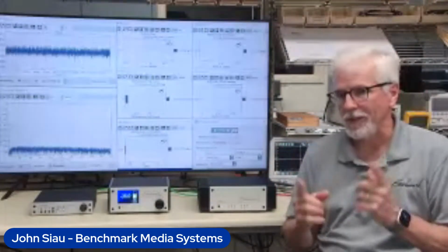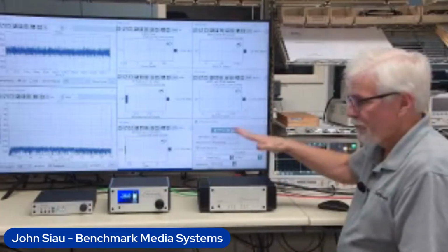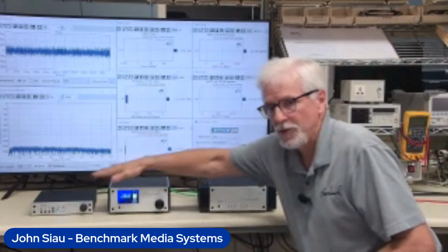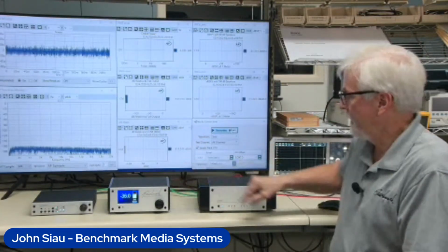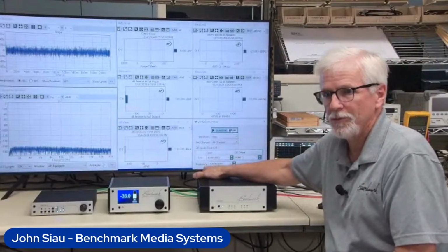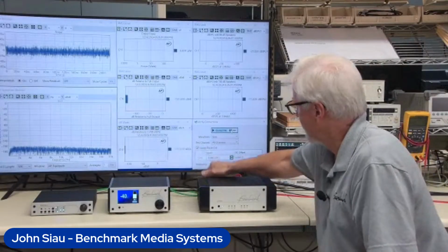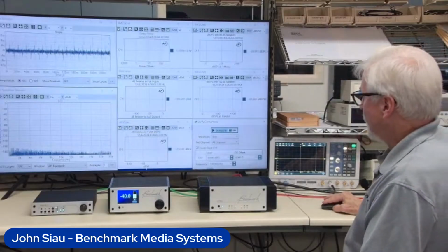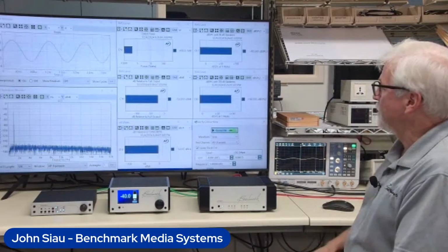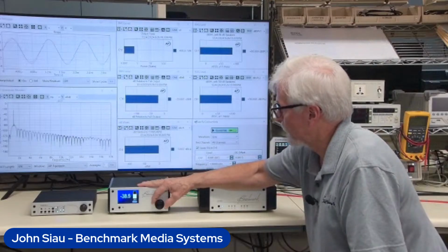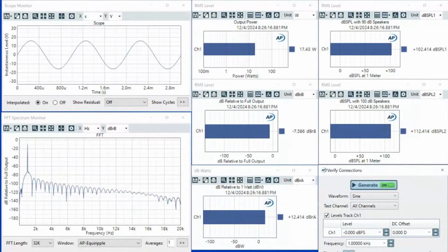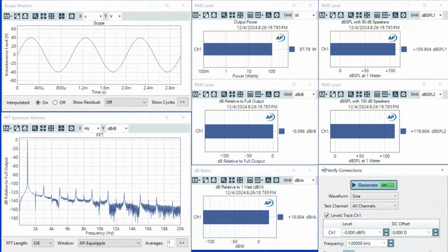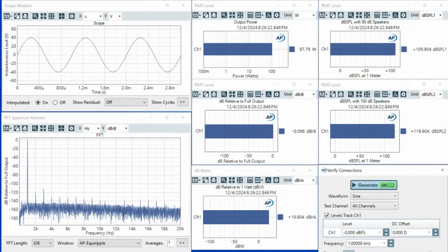But now here's the interesting thing. Let's intentionally misconfigure the gain on these two boxes and try to fix it with the LA4. We're going to find out that it actually works wonderfully. So I'm going to turn the gain up on the AHP2, maximum gain setting. I'm going to turn the LA4 up until I've got 100 watts. Oops, too far. It's about there. Close enough. 0 dB.